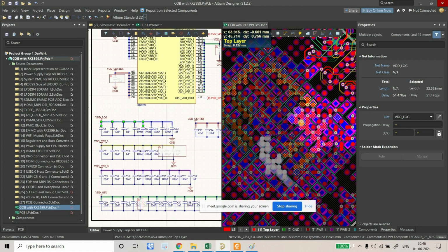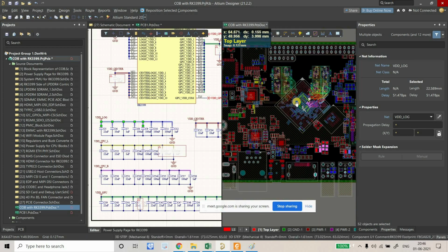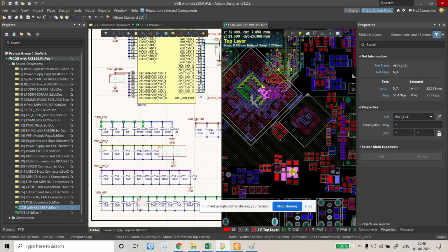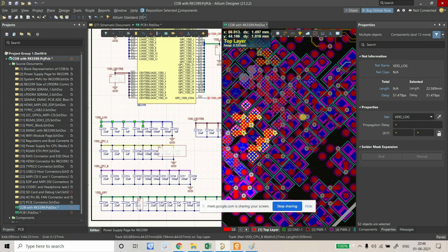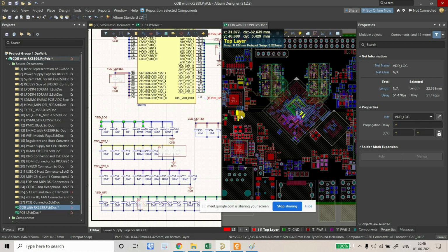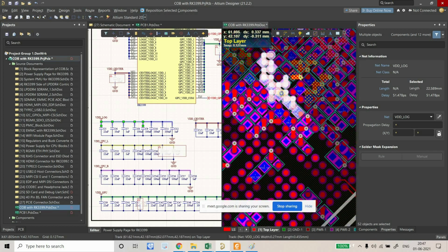Apart from that, this is for, I guess, the big CPU, right? Where that big CPU is going, we have a dedicated buck converter for the big CPU, so it is going like this. Where the little CPU is going, we have a dedicated one as well. Again, this thing we have to place. So this is a part of the PMIC, and this will be going from here. You're getting it? And now let's take this one.